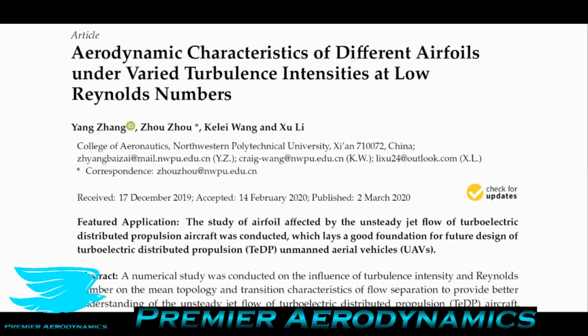For example, I remember maybe about a decade ago now, I was using some CFD software and I wanted to validate it with my wind tunnel experiments. My wind tunnel had a turbulence intensity of like 0.6%, I think, from memory. The CFD package that I had only had 3 settings for the turbulence intensity. It had 0.1, 1%, and 10%. So it was really not ideal, because even at such a small difference in turbulence intensity, it does make a big difference to the airfoil performance.